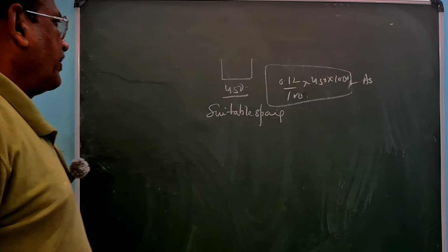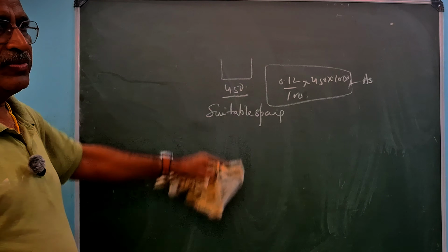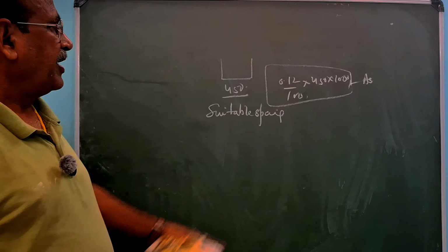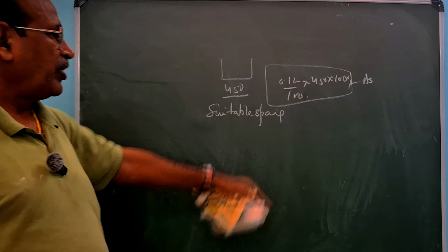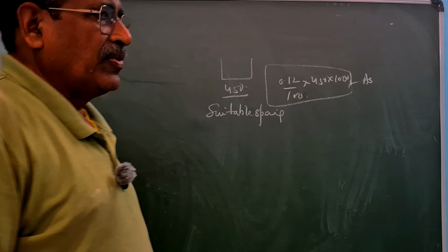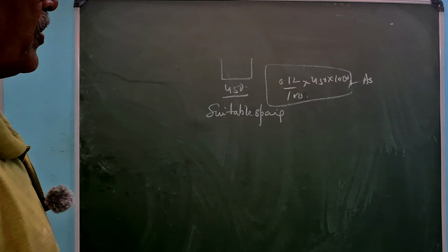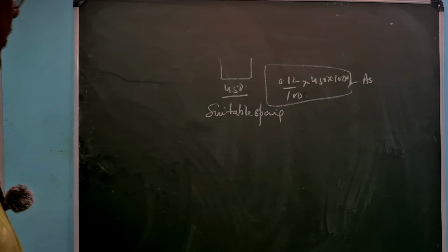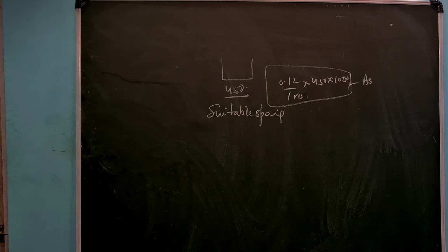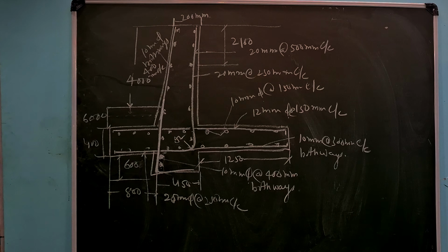जो मेन 10 mm की बार आ रही उसी बार के साथ इसको हम लोग कोरिलेट कर लेंगे, और ये मिनिमम स्टील को देख लेंगे कि इतना 0.12% जो है आपका वहाँ की में जो है आप प्रोवाइड कर दे रहे हैं. तो अब डायग्राम की मदद से हम लोग इसको विजुलाइज करेंगे कि किस तरह से रीइंफोर्समेंट का डिटेलिंग की गई है. तो will continue for the detail. So we can arrange the reinforcement.